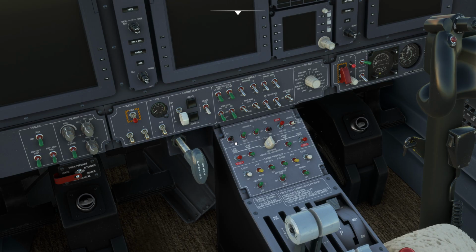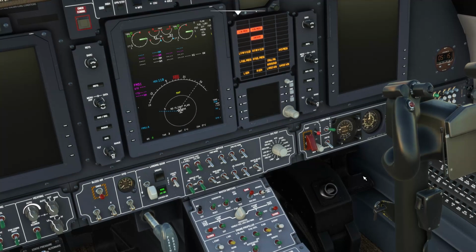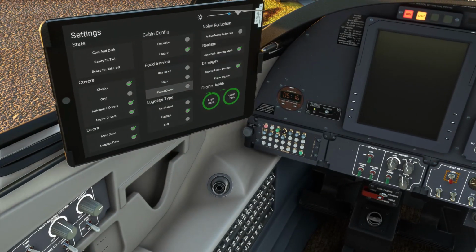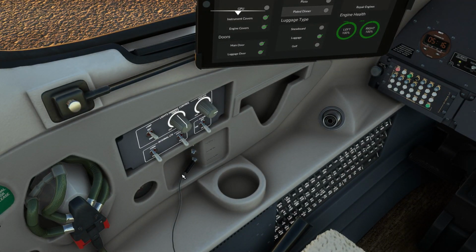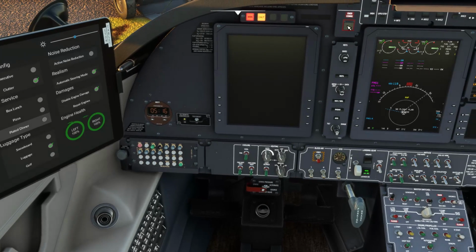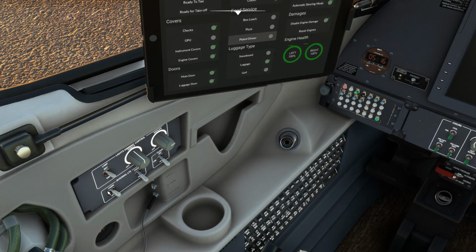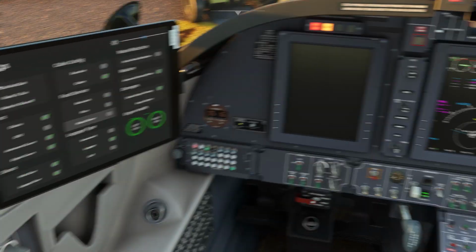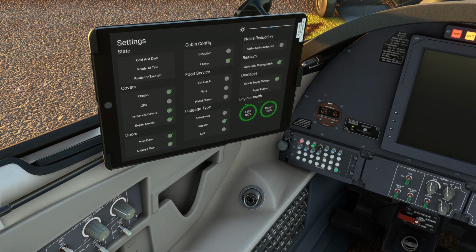So, battery switch. Battery to on. The aircraft has lights by default switched on. So that's your floodlight. We don't need floodlight. That's your cabin. Cabin should be on generally. Lamp, so that's the brightness of your caution light, so we'll leave it at bright. That we don't really need. The control panels and displays, do we want displays illuminated? Not really. It looks like it's a nice sunny day.